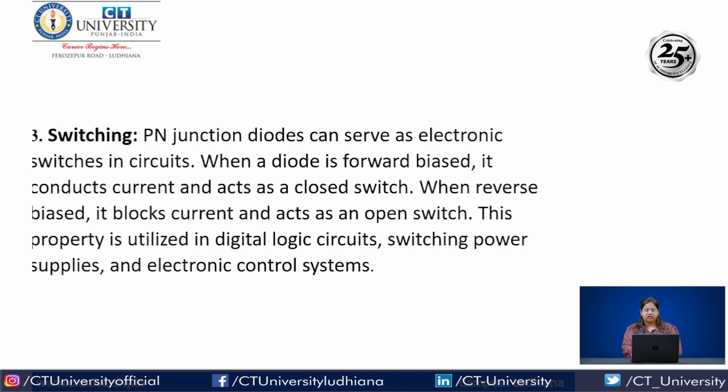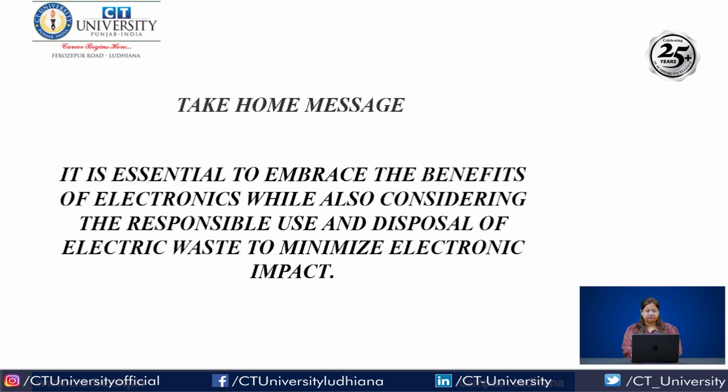Next is switching. PN junction diodes can serve as electronic switches in circuits. When a diode is forward biased, it conducts current and acts as a closed switch. When reverse biased, it blocks current and acts as an open switch. This property is utilized in digital logic circuits, switching power supplies and electronic control systems.